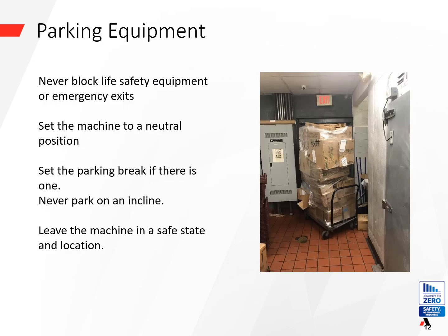Parking mobile equipment. Avoid blocking life safety equipment or emergency exits at all times. Ensure the machine is set to a neutral position before parking. Engage the parking brake if available. Never park on an incline to prevent unintentional movement. Leave the machine in a safe state and location to minimize risks.